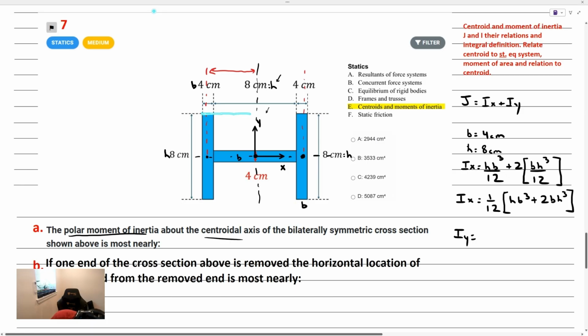I'm going to take the first shape as the entire rectangle shown here, and then I'm going to subtract off these small windows. You could see that if we took a rectangle and subtracted off those two windows, we'd get this I-beam that's on its side. The benefit of this is that these two windows, you can picture they're aligned with the y-axis here. So there is no distance between these shapes' centroids and the overall centroid of the body.